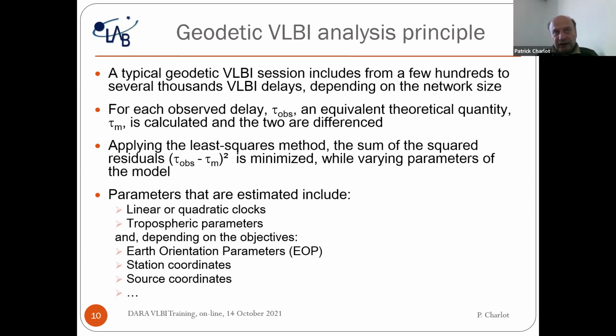What I mean is that at each station you have a clock that gives you the precise time, but these clocks are not perfectly synchronized at different stations, and at the level of accuracy that you work at, this is not enough. So that's why you estimate the difference or the parameters of these clocks.